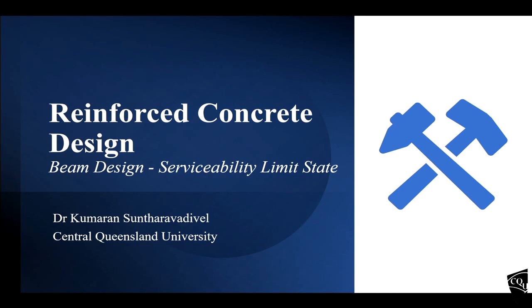If you increase the dimension, what will happen? The dead load will increase. If the dead load increases, what will happen? All your bending moment and shear force will change. So whatever you did, for example the reinforcements and everything, needs to be rechecked or recalculated.